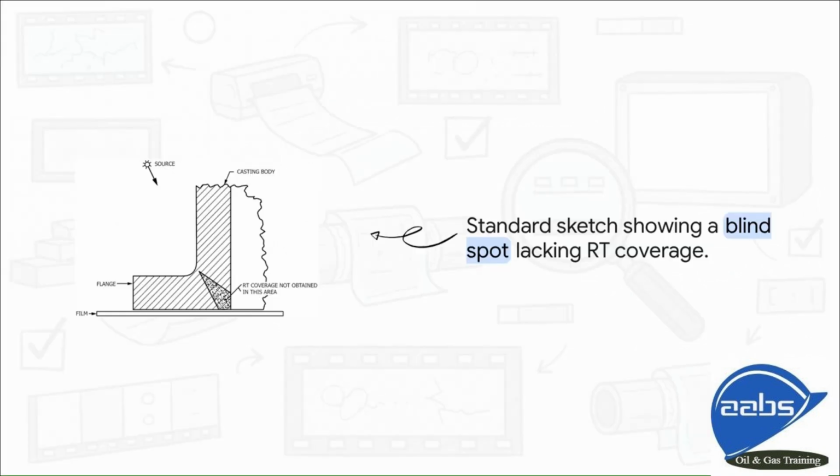Okay, Section 3, Source and Film Alignment. Check out this sketch, because it perfectly illustrates why source-to-film alignment matters so much. Notice the radiation source positioned at the top left, aiming down toward the casting body and flange. Now look closely at that shaded triangular region directly behind the flange corner. As an inspector, you have to recognize this blind spot. Since radiation travels in straight lines, the thicker geometry of the flange literally blocks the rays from effectively penetrating that specific wedge of the casting. Your film just can't capture radiographic coverage there. If you don't map out your blind spots, you might pass a part that's hiding a massive defect right in that shadow.